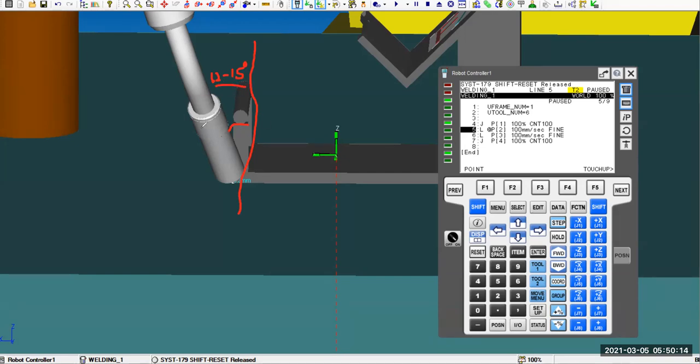So you need to flip the welding gun this way a little bit, then you push towards your welding process, right? In this way, you will have a better welding result. You don't have a lot of what they call spatter, right? So that's a big thing with quality control.